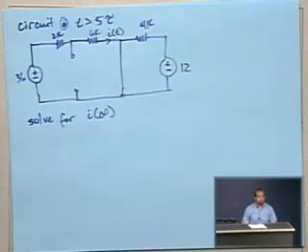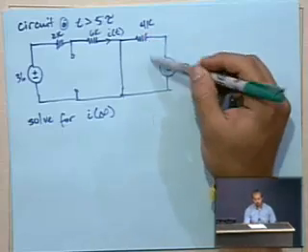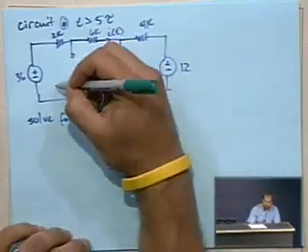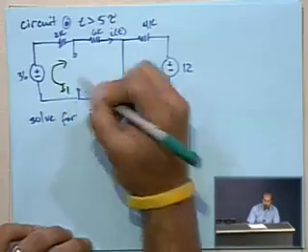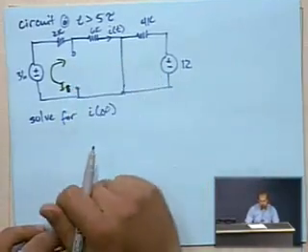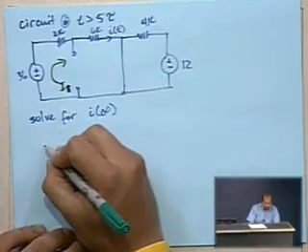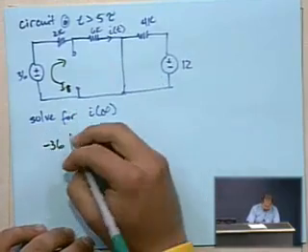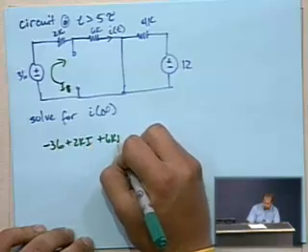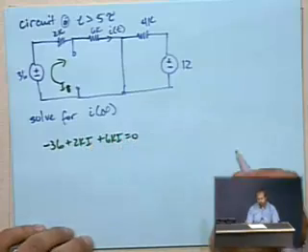Unfortunately, these two loops of the circuit are more or less isolated from each other, or you could theoretically think of this whole right-hand side as being shorted out by the switch being closed. And so if we just write the one KVL equation around that loop, let's just call it I, we get negative 36 plus 2K times I plus 6K times I equals 0.